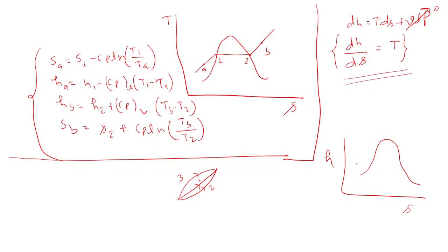So in the subcooled region, when we are giving heat to the water, what would be the shape of the curve? The slope will be increasing, right? Of the three options, we have to go from here to here anyhow. So it will be the second one, since here the slope is increasing. Initially I drew only a straight line, so that was wrong. You have to make it this way.